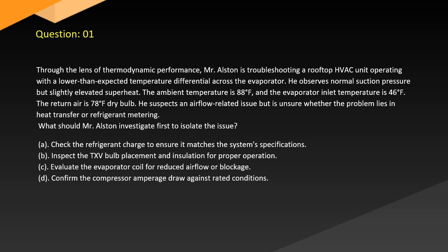Question 1. Through the lens of thermodynamic performance, Mr. Alston is troubleshooting a rooftop HVAC unit operating with a lower than expected temperature differential across the evaporator. He observes normal suction pressure but slightly elevated superheat. The ambient temperature is 88°F and the evaporator inlet temperature is 46°F.